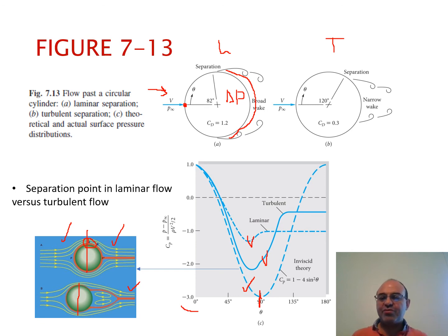So this is very important. This has very important consequences because when we want to design something, it is important to know when the separation point occurs and how the pressure drag, friction drag, and total drag change, in order to be able to reduce the drag force.